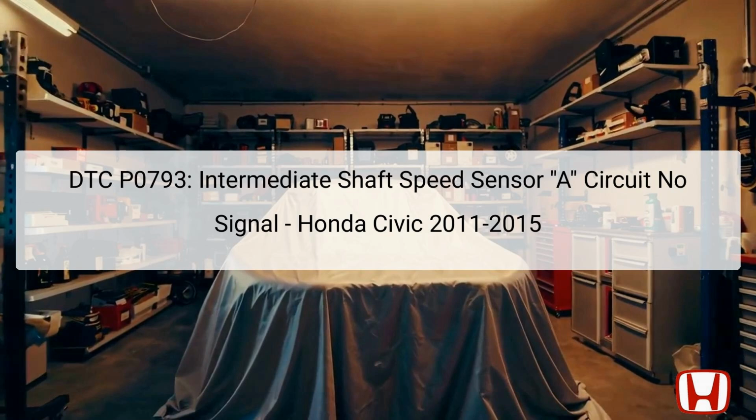It communicates this data to the engine control module, PCM, which uses the information for optimal shifting and overall vehicle operation. Since this error stems from an electrical circuit issue, a mechanical transmission problem is not the root cause. Electrical issues can include problems with wiring, connectors, or the sensor itself, and the troubleshooting process is necessary to identify the exact cause of the malfunction.